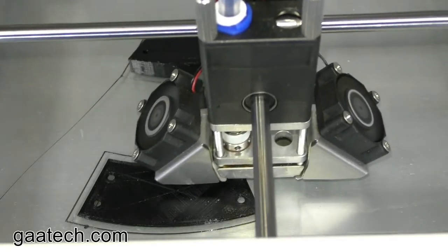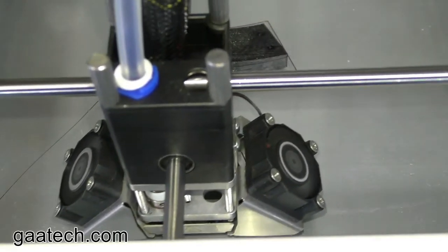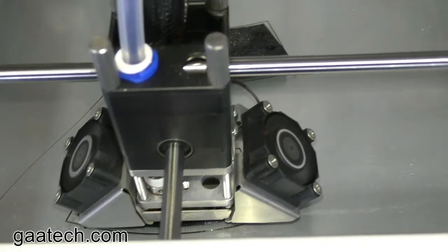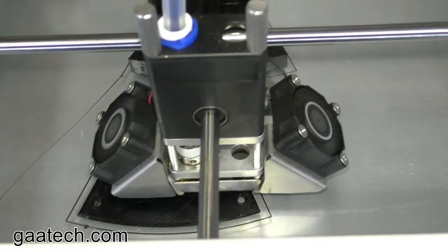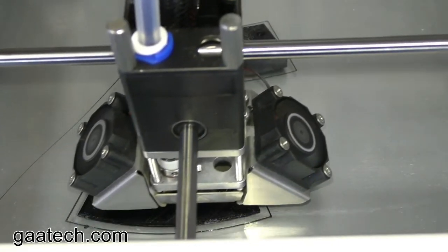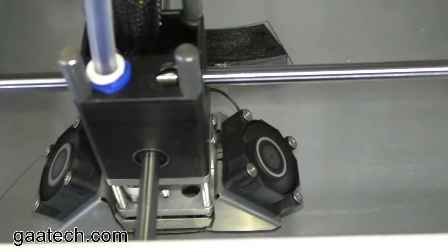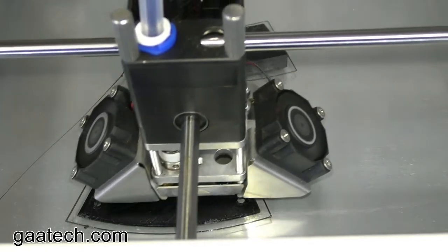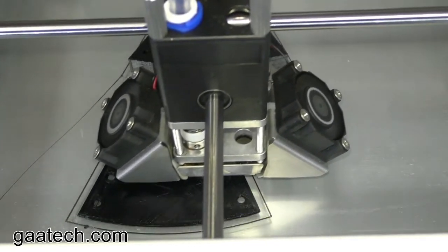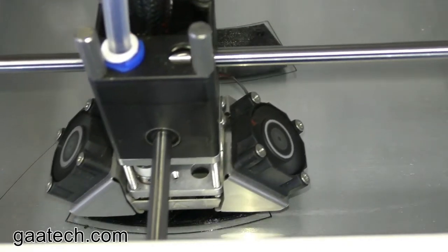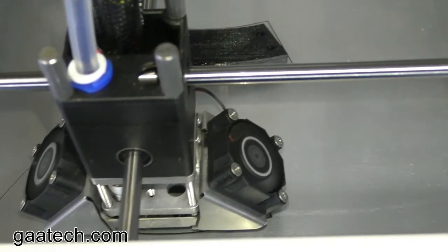The arms on the ZMR 250, and I'll just splice in a picture of that into this video, has 4 individual arms, and he wants a uni arm, so the arms are joined together, so you only have 4 mounting bolts instead of 8. Plus the arms are in one piece, so technically it's stronger.